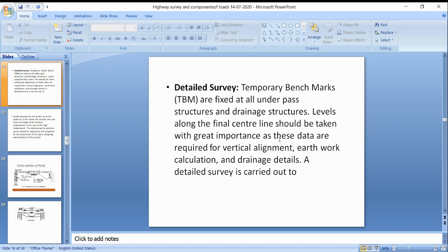At the time of the topographic map, it might not have had some features like natural water sources that may have come up in the last few years. So that data also we can see in the preliminary survey. Next comes the cultivated area: how much area is cultivated, that also we have to see. We also have to see the soil particulars and all other particulars of a site which affect the final position. We have to get all this information in the preliminary survey.